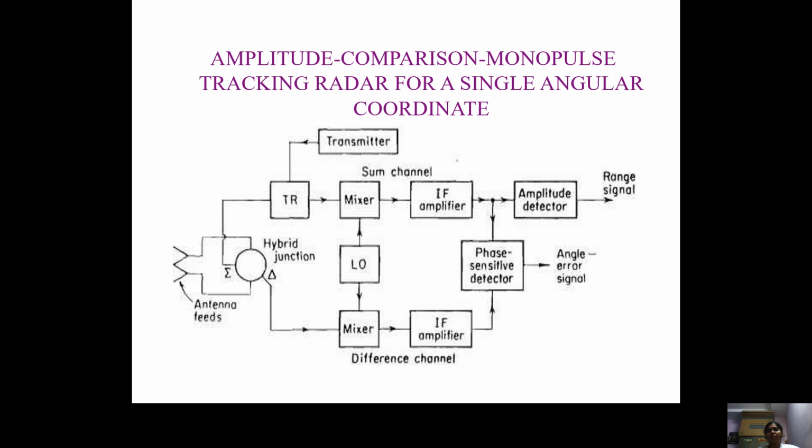The local oscillator acts as a coherent oscillator to maintain the phase shift, the same in both the difference pattern and the received echo signal. The mixer generates the sum and difference of the transmitted and received echo signal, where the high frequency carrier can be eliminated, and only the signal of our interest, the low frequency audio or video signal, is retained.